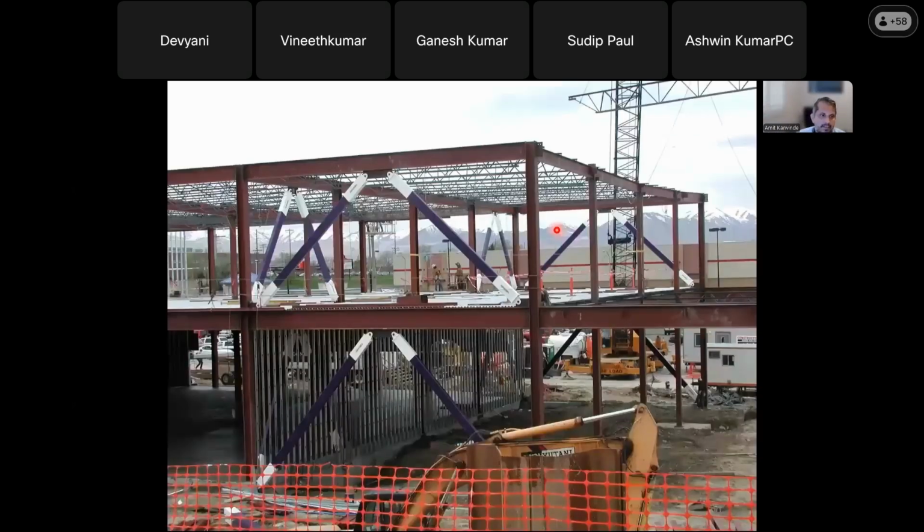Okay. And here are some examples of buckling restrained brace frames. The system started in Japan as a supplemental damping system, but in the United States, it's actually been adapted as its own structural system. So in fact, we'll put these kinds of buckling restrained braces in buildings where all the other connections are pin connections. So these BRBs, as we call them, are the primary lateral load carrying mechanism.